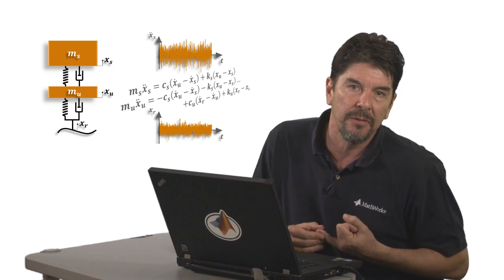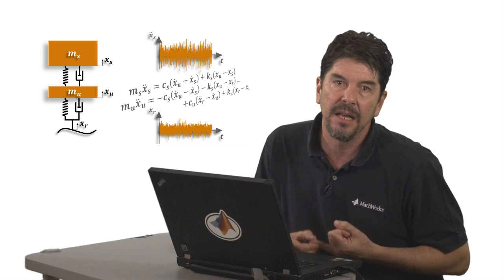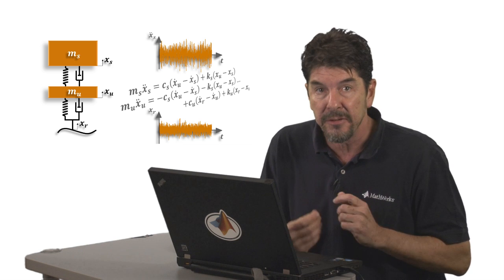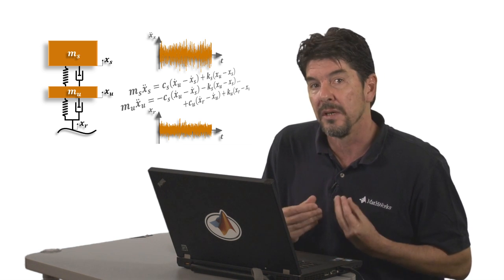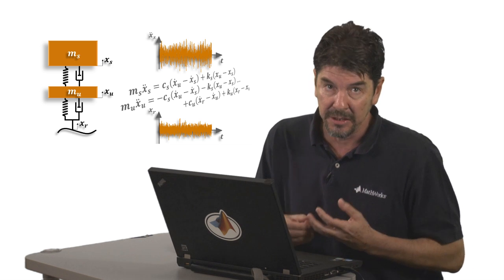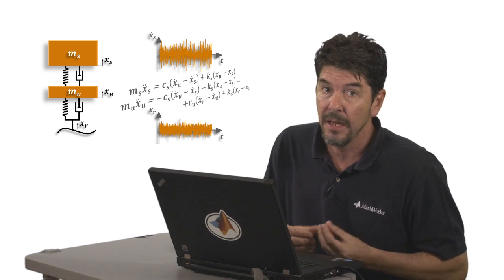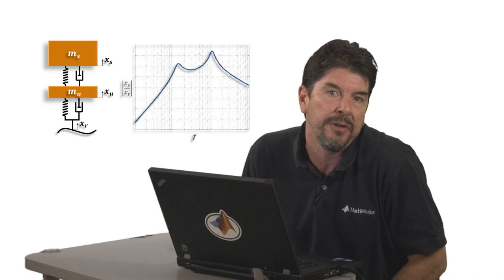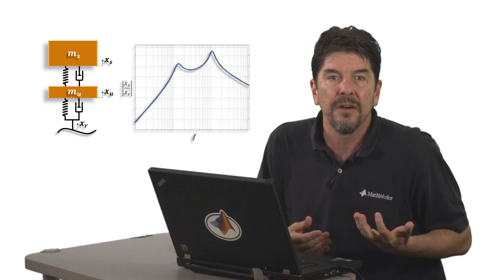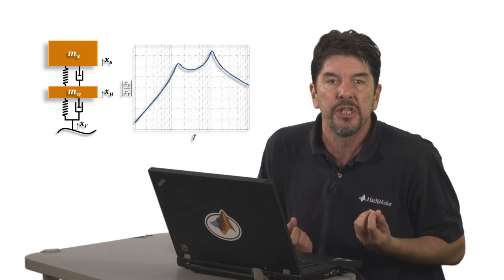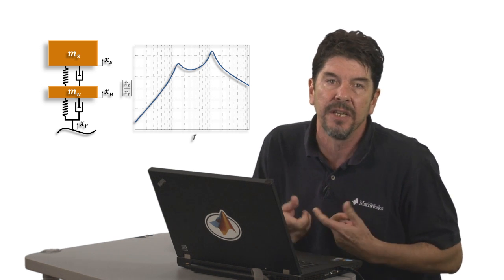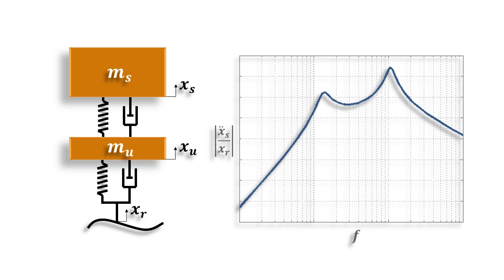Here's where the genius of people like Fourier and Laplace comes into play. A Laplace transform, for example, will help us convert this forced differential equation problem that can be very difficult to work with in the time domain into a simpler algebraic set of expressions based on the complex Laplace operator S. Once in the frequency domain, we can easily create a plot of the response of the system for a bunch of different frequencies. You can think of this diagram as the ratio of the amplitude of the energy transmitted from the road under the tire up to the acceleration of the car body.